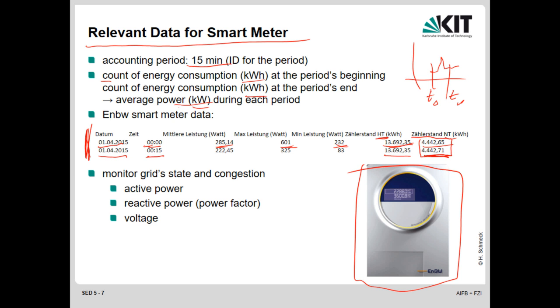I guess that Discovergy, as I said, provide data on a 1 hertz basis. That means every second they will send different information. You could also send things which they do not send, like reactive power. So the power factor would also be of interest. What is the local power factor? The deviation of voltage and current. And you could look at the voltage. The voltage is not measured here.